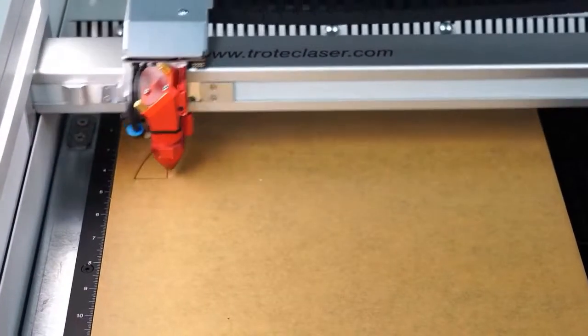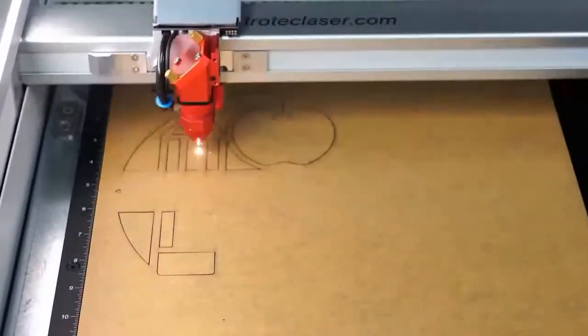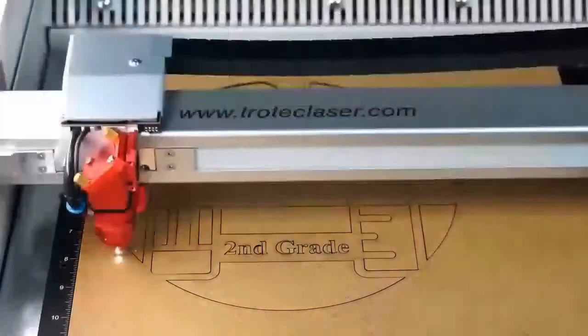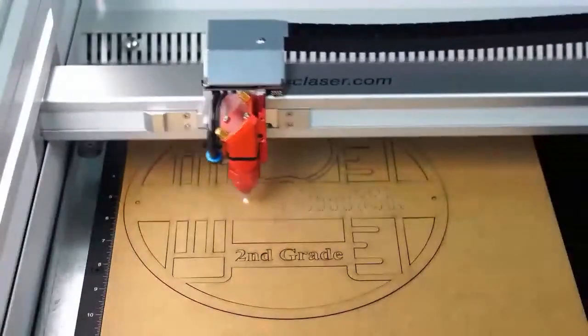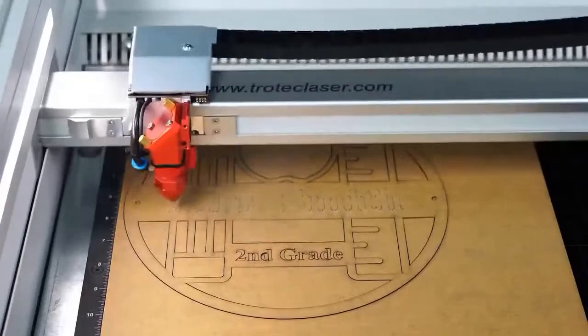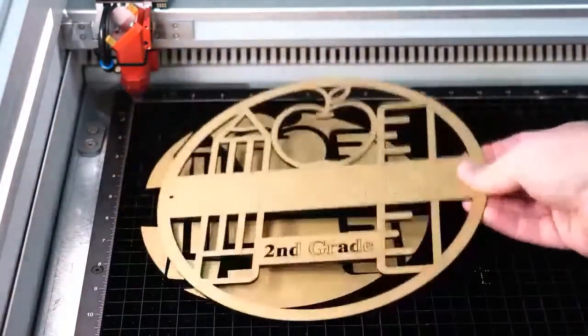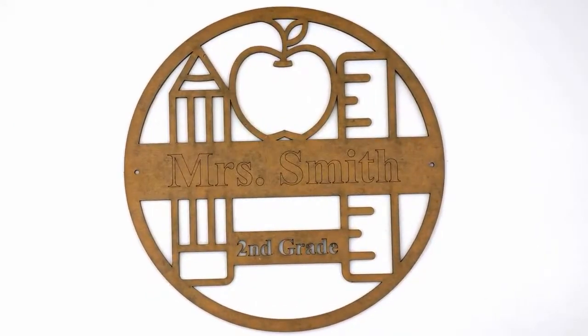The laser will then go ahead and cut out all the red color. In this case, I did 2 different colors. The red color is going to be identified by the Ruby software as a cut path, and then here it's cutting out the blue color. The blue color is a score or a marking setting, so it's not cutting all the way through, but it's producing an outline of where the letters will be.